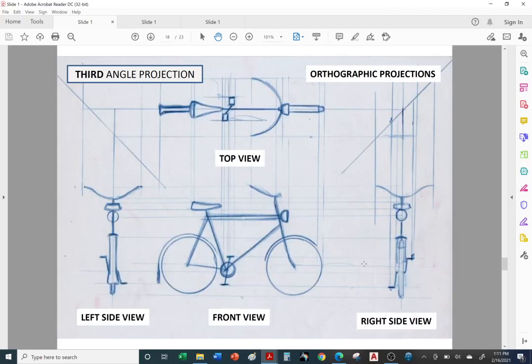Okay, now let's take a look at a bicycle. Now, even though we know that this is the front of the bike, this view has more information. Okay, so this view we're going to call the front view. There's a lot more information in this view, so we'll call this the front, even though it's not the front of the bicycle. And then project 90 degrees. So again, just like Jack, turn to your right and step back 2 steps, and that's your right side view. Come back to the front, face the camera. Okay, turn to your left and take 2 steps back, and so on.